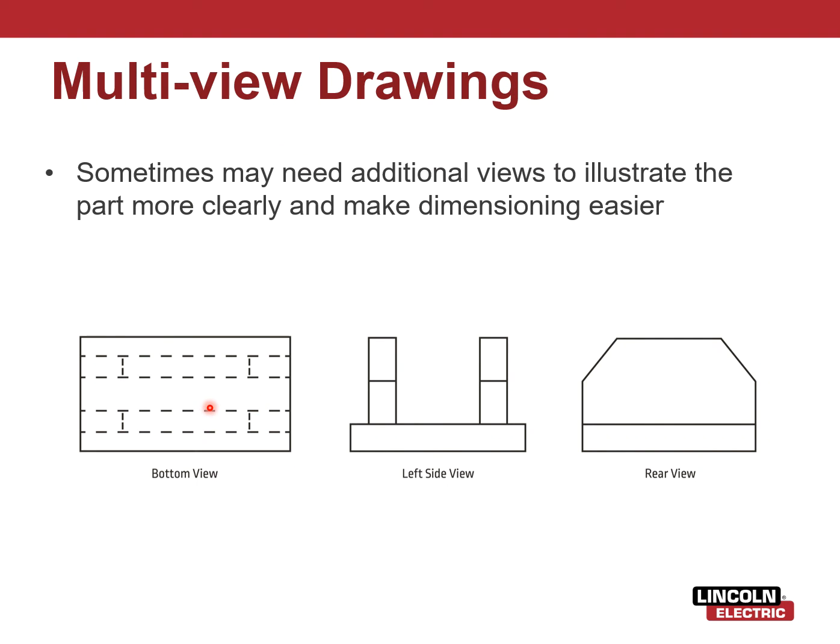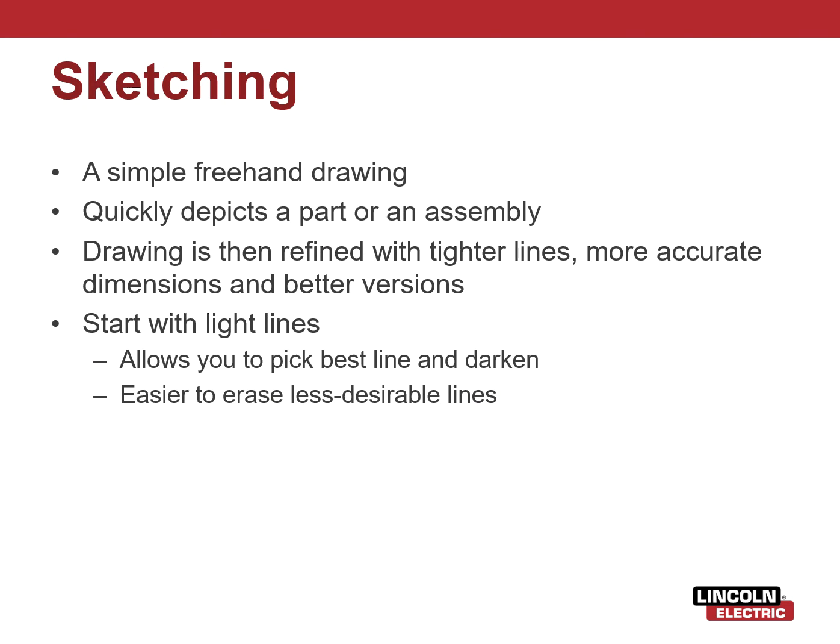Then you'd also, like we mentioned earlier, a bottom view, left side view, rear view. Sometimes if you need extra detail, maybe there's something unique about one of those sides, then you would include one of these if that was the only way to convey the detail of that part. So it's meant to be done in as few views as possible.